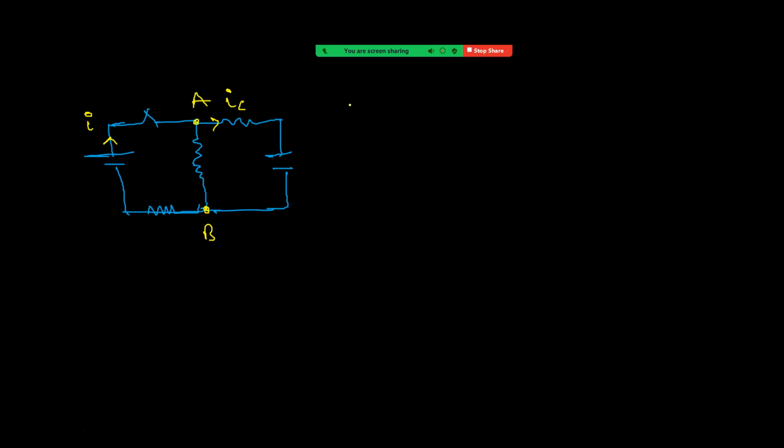And we got Q equal to Q naught, and the value of Q naught is C into V by 2 into 1 minus e power minus t by RC. We got the tau value as 3R by 2 into C. So this is 2t by 3RC, right? This is the charge as a function of time.